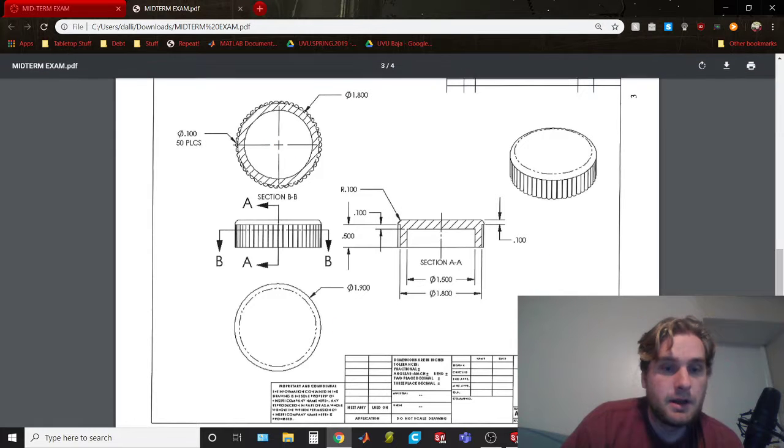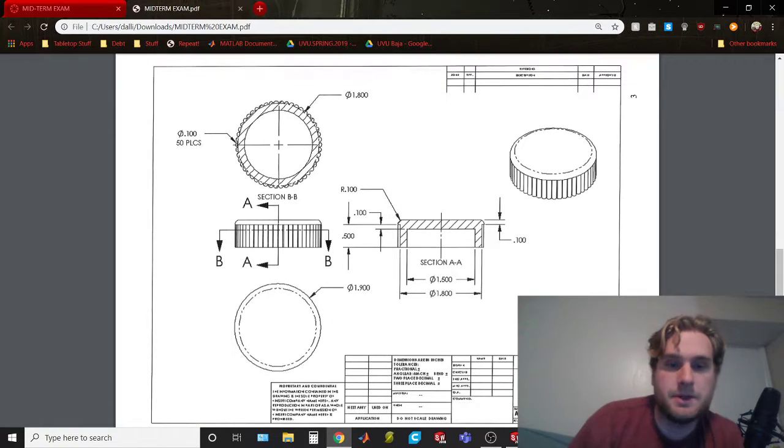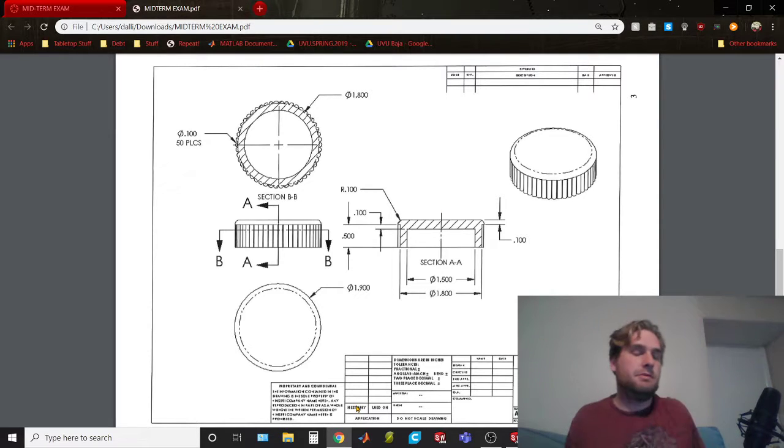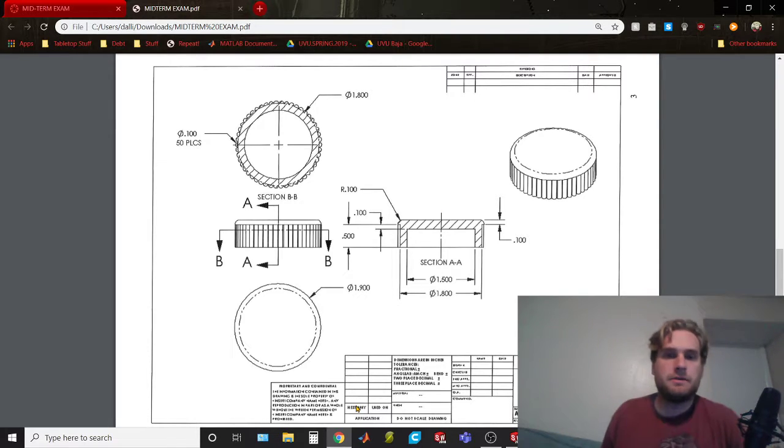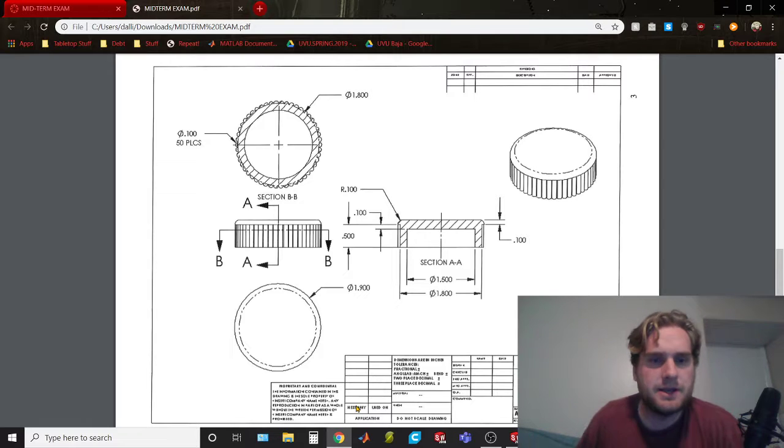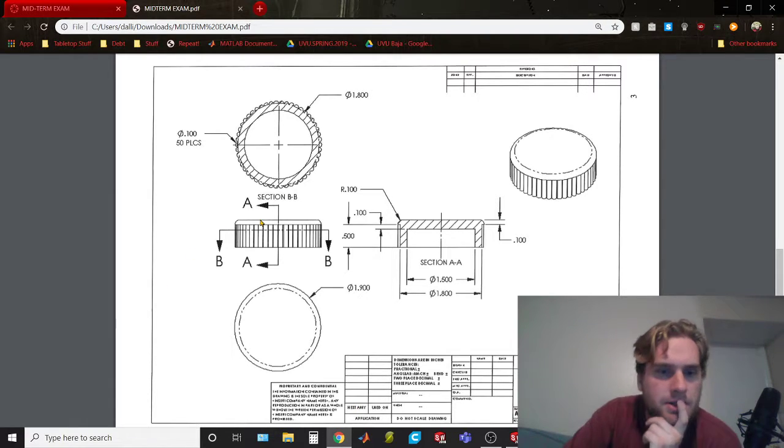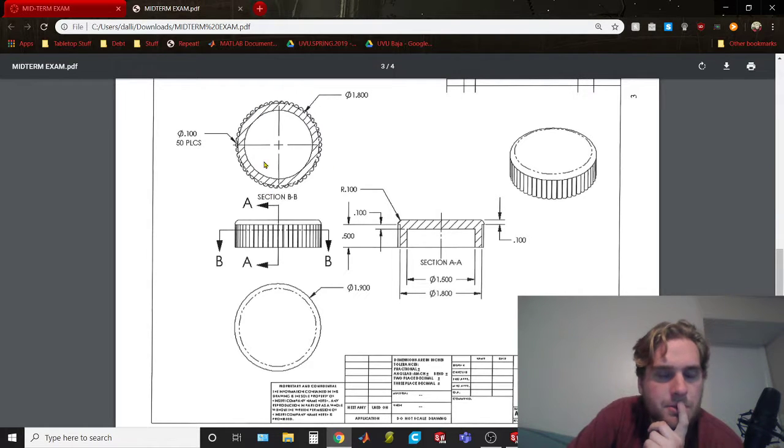Alright. So, once again, what do we see? We have an axis of rotation. So, we can do the same thing we were doing before. Just create part of it and then do a revolved boss/base. We do see there's 2 section cuts, though. And it's interesting to note that essentially we have a rigid top and that these little ribs that we can see here on the side, I think it's pretty important to note that those are essentially cut down from the solid top.